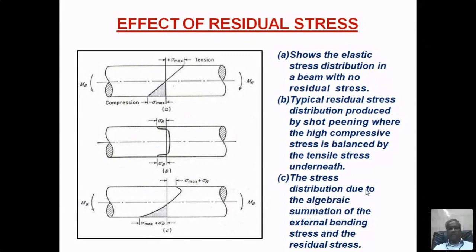Okay. And another metallurgical variable, grain size, yes, it has an effect. Grain size, especially it is having an effect on the high cycle fatigue region. Low stress, high cycle fatigue region, it has the maximum effect. Grain size: finer the grain size, the fatigue strength will be higher, fatigue life will be higher. Coarse grains, the fatigue life will be lower. So by grain boundary strengthening mechanism also you can improve the fatigue strength. Grain boundary strengthening, fiber strengthening, second phase strengthening, cold working. There are many strengthening mechanisms. So that will also, by increasing the tensile strength, you can increase the fatigue strength.